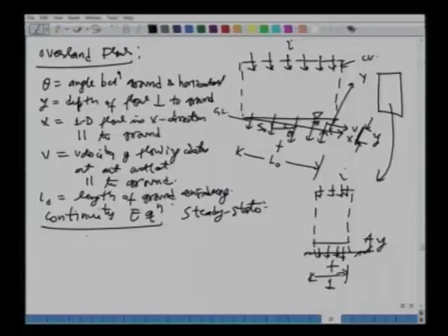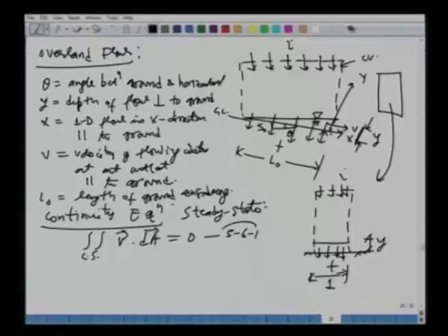So, your continuity equation will be the double integral over the cross section or surface of beta rho v dot dA, plus the accumulation term. Beta is 1, and rho can cancel out or come out. So, all you have is the integral of v dot dA equal to 0, and this we will say is 5.6.1.